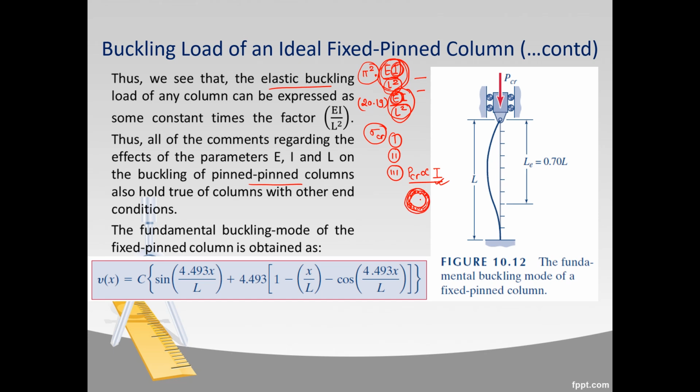However, one thing to remember when we are using these thin-walled columns is that the thickness of the wall should not be so thin that local buckling can occur. So you have to differentiate between global buckling and local buckling. Our thickness of the column section should not be so small that local buckling may occur. That local buckling will induce a failure in our columns also, so we must make sure of that too.